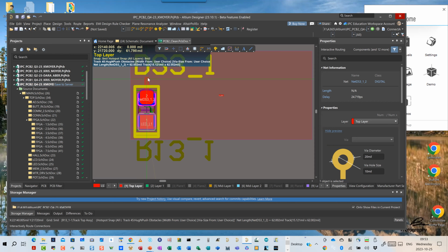But for normal routing, like we just talked about with the control impedance, we're going to try and have one layer primarily horizontal, one layer primarily vertical. So the any angle kind of mucks with that a little bit. So I try to stick to the 45-degree. It's a good bread and butter one. I've used the any angle occasionally for special cases, but for the most part, no.